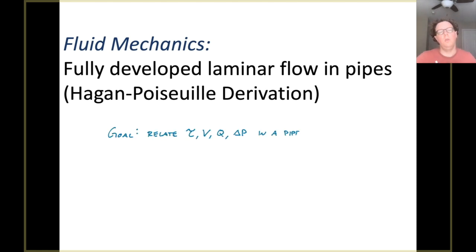We know that when flow is moving through a pipe, there is a velocity and a flow rate associated, and there will be a shear stress or a loss of energy associated with friction arising between the edge of the pipe and the fluid, and also fluid-to-fluid friction. The result is that we're going to generate a pressure drop due to those losses. So our goal here is to describe that pressure drop as a function of the fluid, the pipe, and flow rate. That's what we're after today.